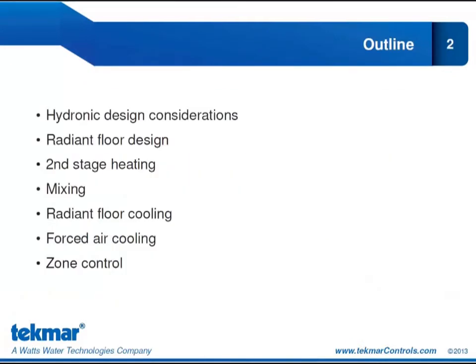The outline for this presentation is to bring up the hydronic design considerations, namely our entering load water temperatures. Then we'll look at radiant floor design and second stage heating. Now normally we can't satisfy the building needs with a radiant floor only. We do need to introduce second stage heating. And that means we're going to be requiring mixing. So we'll talk about the concept of mixing and how we can design and control that.